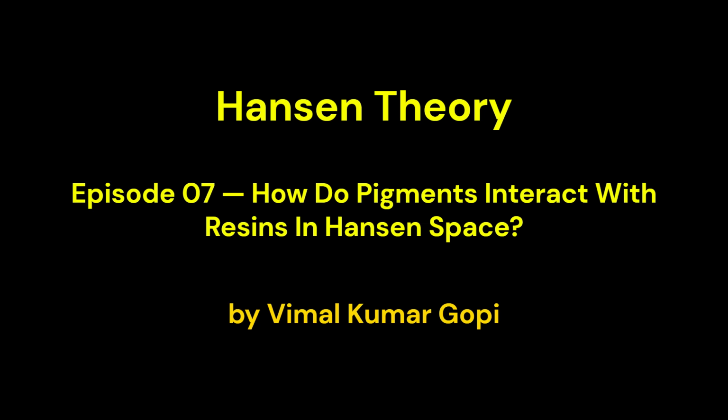Here's an example. An automotive primer uses titanium dioxide. The polymer has a solubility sphere centered at specific delta D, delta P, delta H values. The pigment surface interactions sit far from the polymer center. Without a proper dispersant and solvent blend, red exceeds 1. Result: flocculation, poor opacity, settling. With proper calculation and adjustment, the effective pigment-resin system moves closer to the polymer center. Red drops below 1. Dispersion stabilizes. Opacity and gloss are optimal.